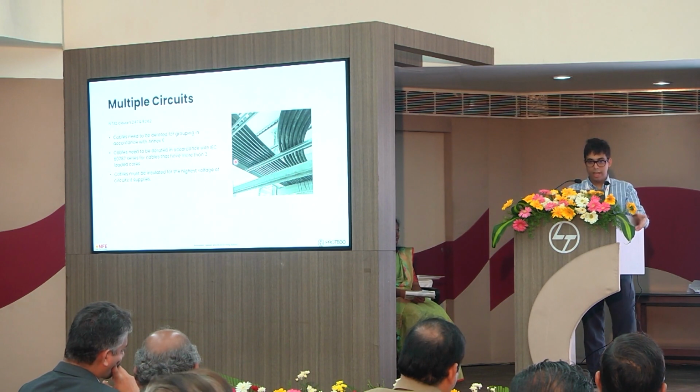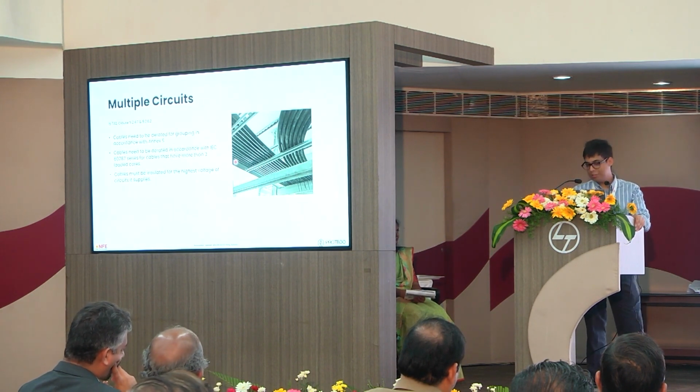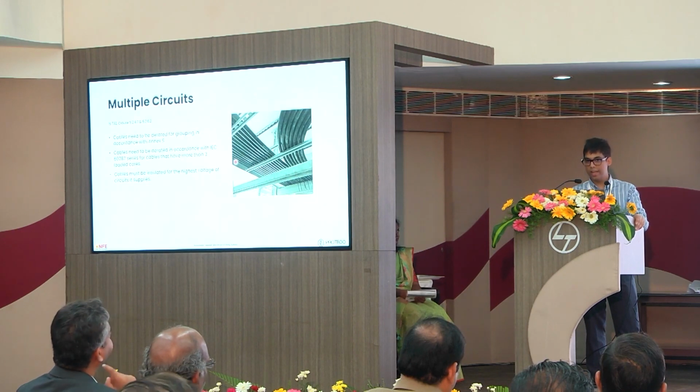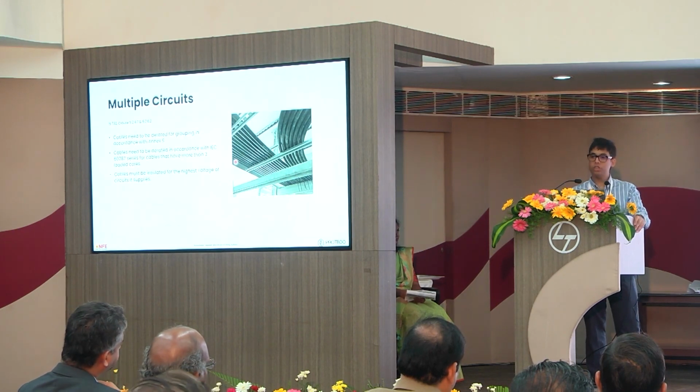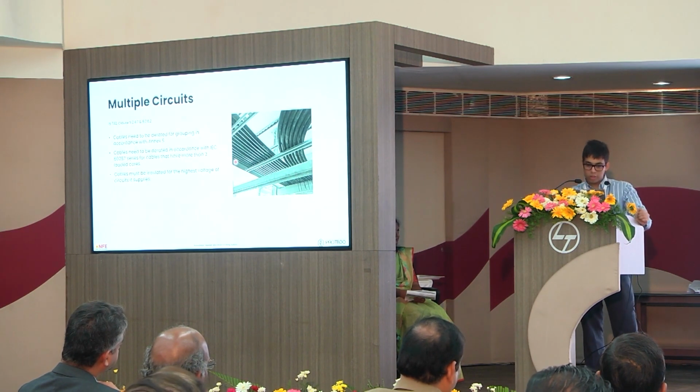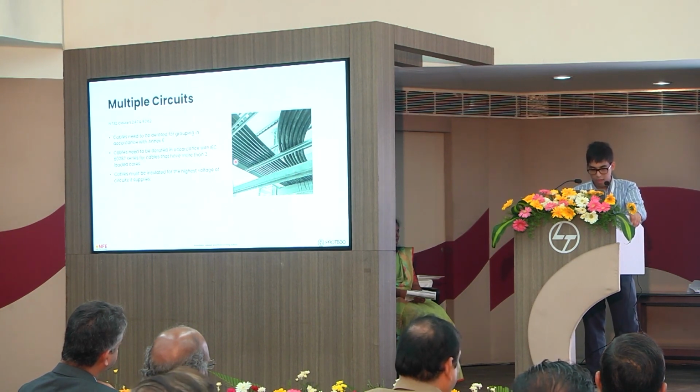Yes? Exactly, which is why Annex S of IS 732 and part of Section 9 in SP 30 goes into derating factors. So if you're running multiple cables together, let's say 2 circuits, 3 circuits, you're going to have to use a reduced current carrying capacity. We'll go into the factors slightly later on in the presentation.